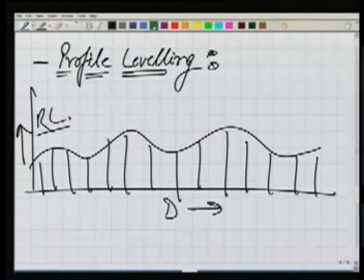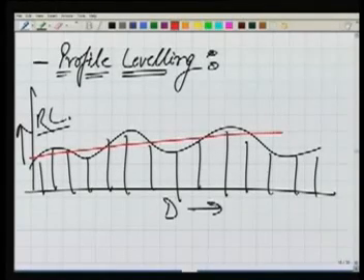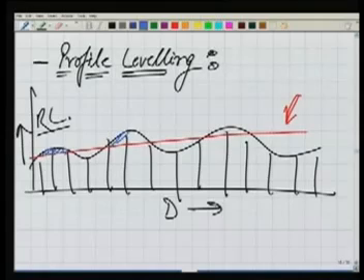This profile is very important in many applications. If you are going to lay a road in that particular terrain, you would like to know the formation level for the road should be such that the amount of cutting, all the blue shaded is cutting, should be equal to the amount of filling, all this red shaded is filling.